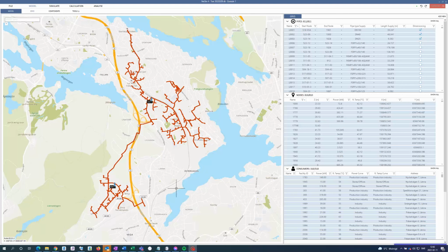After that is done, we usually also import consumer data. So that's usually some powers and temperatures. We can work with generalized return or delta T's if needed, but best case scenario, we have some return temperatures or delta T's measured from your clients together with some form of power. And we usually use a maximum measured power during last year or so, of course with some filters and so on to make sure we don't have any erroneous values getting entered.